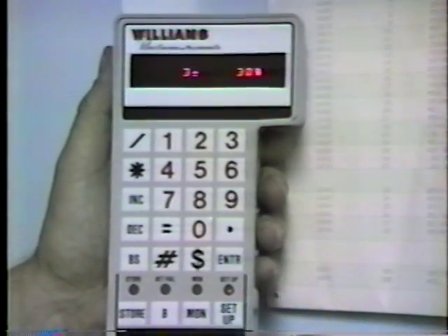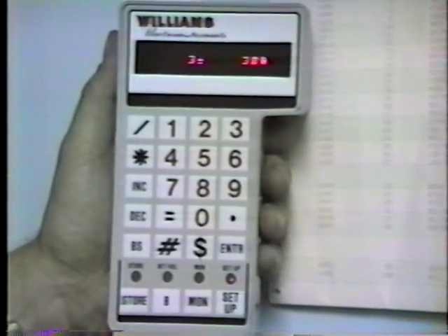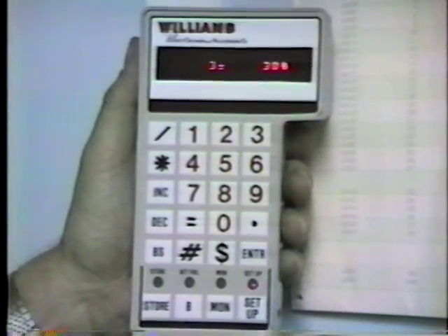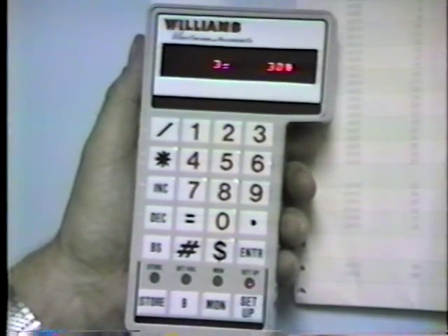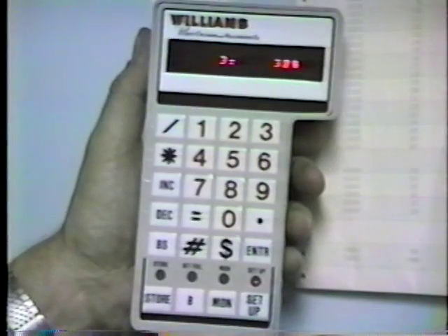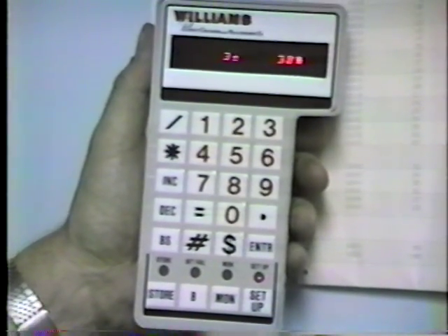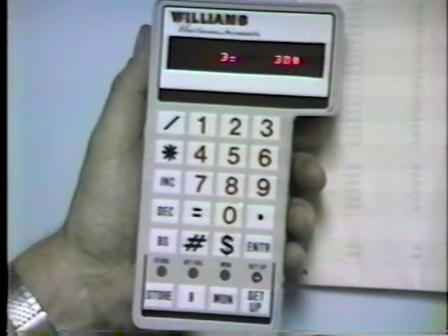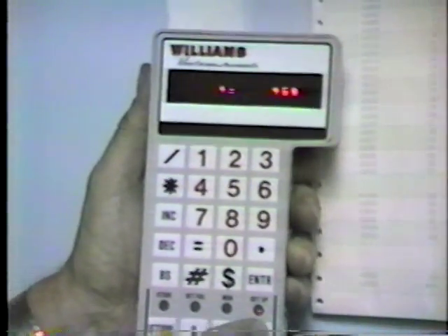The spinner speed is used to increase or decrease the fineness of the product being burned. Higher percentage gives you finer. So we have set this at 30 and have determined that at that setting we get 91 to 92% minus 200 mesh. The normal is 70% minus 200. So any finer is kind of ridiculous. Would you go ahead? Now, would you show the next one?